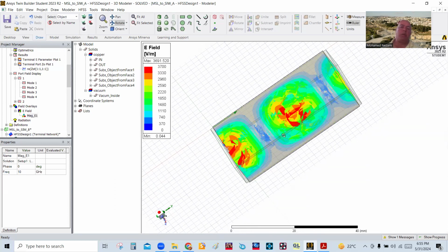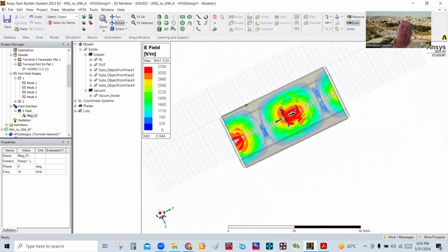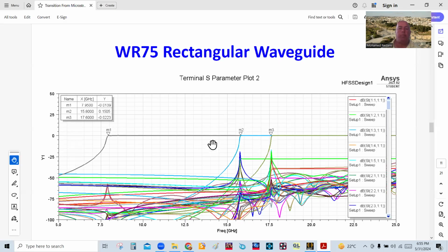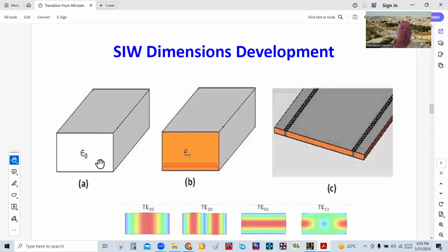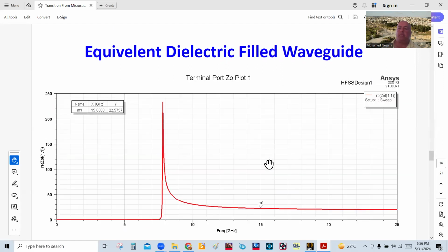But you can see the mins and maxes in here, the complete half wavelength pattern is only, like in this case, a half here, well, a third here, a half here, and a full one here, versus when you go to the other one. Okay, so basically what we did is we went from a conventional rectangular waveguide to a substrate integrated waveguide, and then with an intermediate transition to the direct field waveguide, okay? And we proved that it is exactly the same.